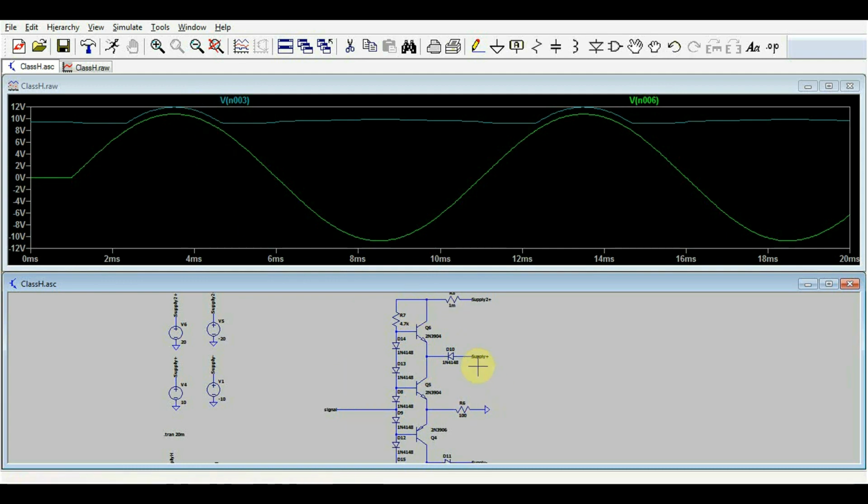So this sort of circuitry will keep the benefits of the G-class amplifier, so by using multiple supply rails, but it will also keep the output signal unaffected, like a typical AB class amplifier, since there's no sudden variations of the supply voltage. And this is basically the last type of analog amplifier that is currently used in audio applications.